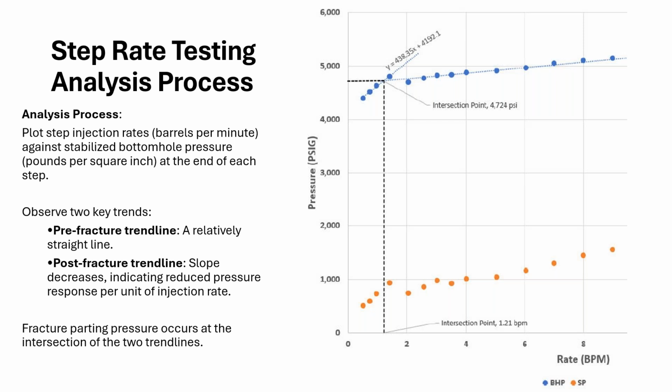You can have a very low pressure on your 0 rate curve, or you can say that this is wellbore storage effect going on in these initial rates as the wellbore fills up with fluid. And then you can note that the hydrostatic dynamics of that fluid column are going to change with the pressure effect, the temperature effect, the density effect, and viscosity change in the fluid that is in the wellbore versus the injected fluid. These can be noted in your analysis, and it's important to do so.